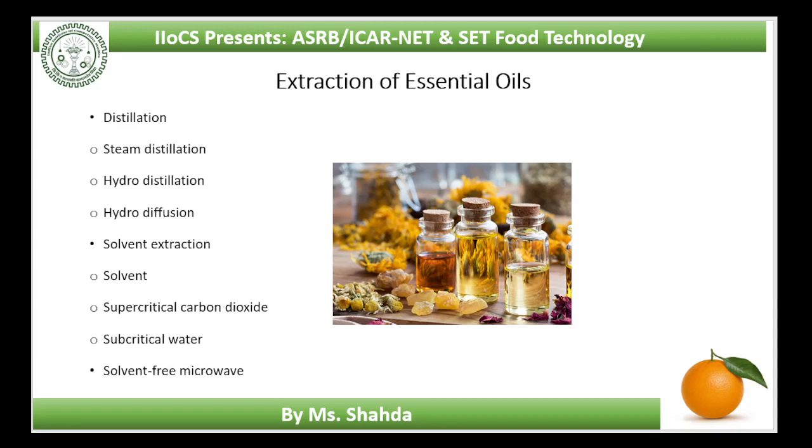Hydrodistillation has become the standard method of essential oil extraction from plant materials such as wood or flour, which is often used to isolate non-water-soluble natural products with high boiling point. The process involves the complete immersion of plant materials in water followed by boiling. This method protects the oil extracted to a certain degree, since the surrounding water acts as a barrier to prevent it from overheating. The steam and essential oil vapor are condensed to an aqueous fraction. The advantage of this technique is that the required material can be distilled at a temperature below 100 degrees Celsius.